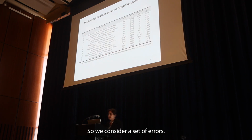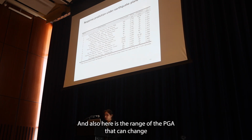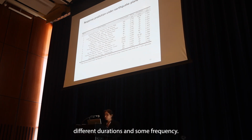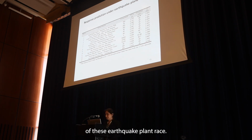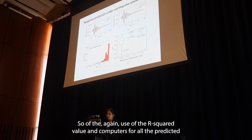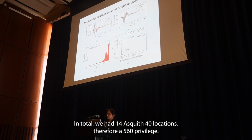Then as a second step, we consider a set of earthquake plane waves, 14 of them, that are listed here at different stations for different events. And also, here is the range of the PGA, and the different durations and dominant frequencies. We wanted to see how this model is doing in terms of predicting the response under these earthquake plane waves. So we again use the R square value and compute that for all the predicted responses at the different locations over the buried structure. In total, we had 14 earthquakes, 40 locations, therefore 560 predictions that we did.